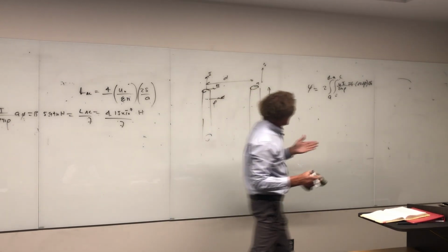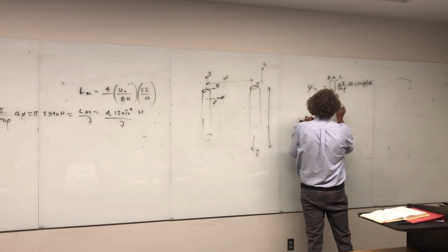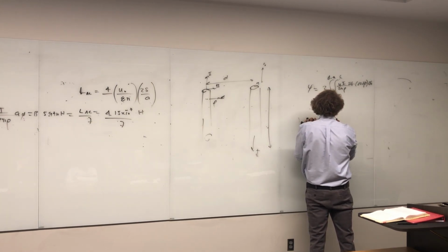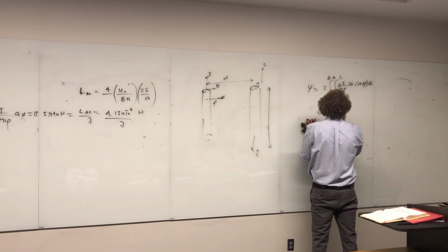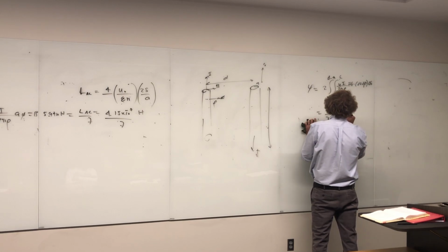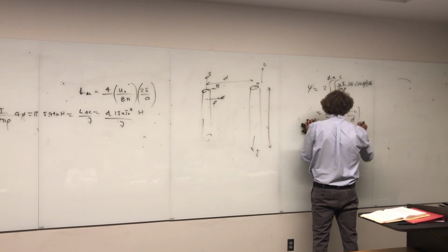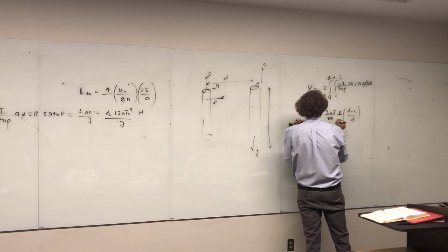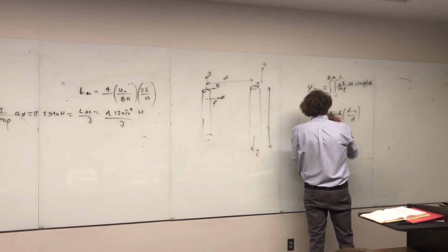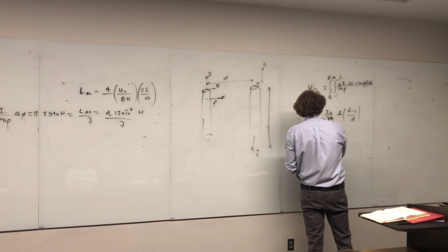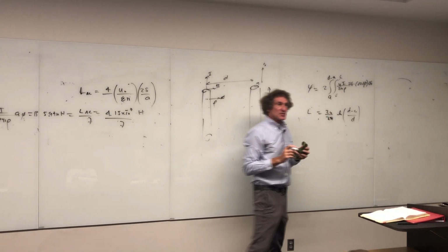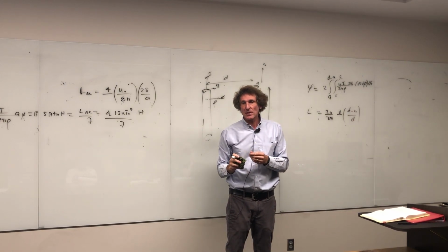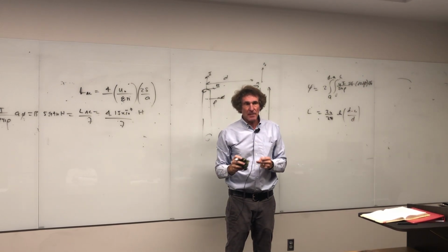Now, what is that going to come down to? Well, that's going to be 2 over 2 pi, I, then mu. Then it's going to be the natural log of D minus A over D. That's a 2 pi there. Then I divide that by the current, just get rid of that current, and now I have the inductance of those two wires, the external inductance. Does that make sense? If you don't understand some portion of this, look it back up in Emag2. It's a straightforward method of doing this.